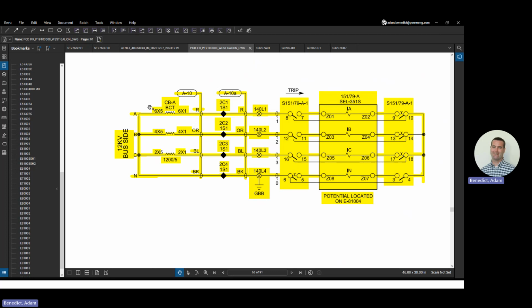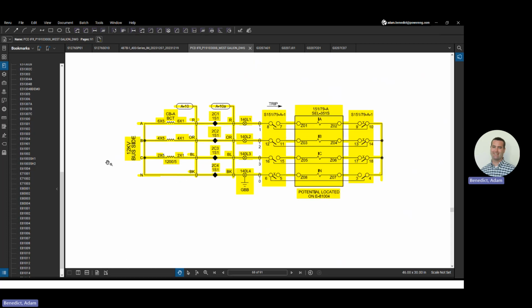And this takes that extra level of verification where you don't have a breaker. You're not showing your lines, your breakers, your transformers. So you really need to bounce this against the one lines, the vendor drawings, and the EAs to make sure your phasing is right. You're using X instead of Y, and then what side you're on is accurate. It's not my favorite way to show it, but it is what it is.